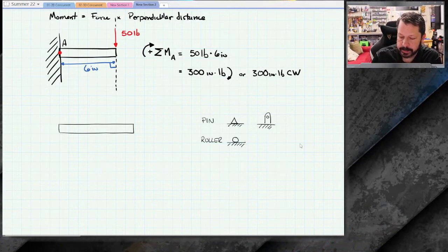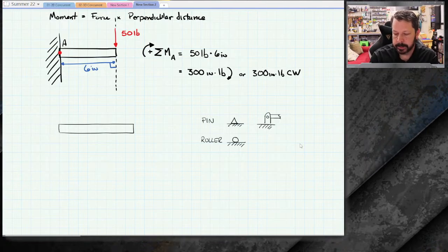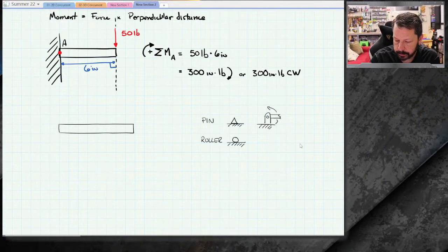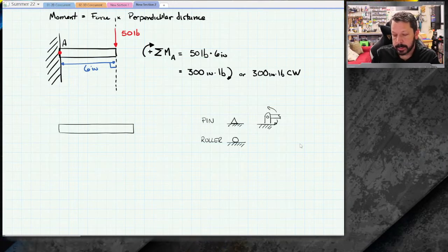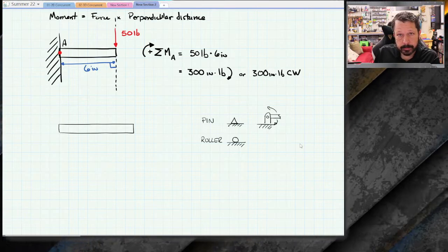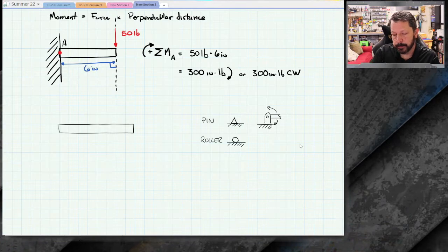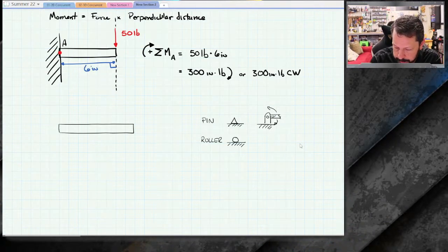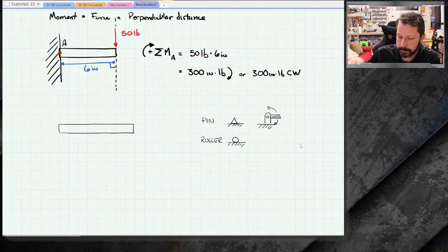There's some kind of clevis there, and then I've got something attached to it, and this thing is able to move around, right? It can swing around one way or the other. So what the pin is doing is it's constraining motion left and right, up and down, but it's allowing this piece that I connected to it to swing around it, like rotate around it.